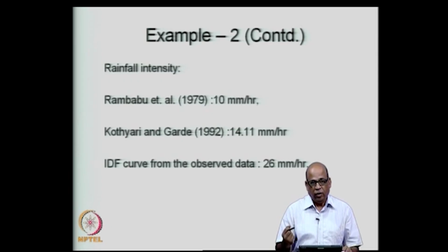held fixed, and we must have a mechanism by which we are able to project, given a particular IDF relationship today, in what way the IDF relationships are likely to change in 2 decades, 3 decades, the 2020s, 2040s, etc., because the hydrologic designs that we are putting in place today are supposed to serve us for the next 30 years, 40 years and so on, and therefore, we must be able to use the corrected IDF relationships.